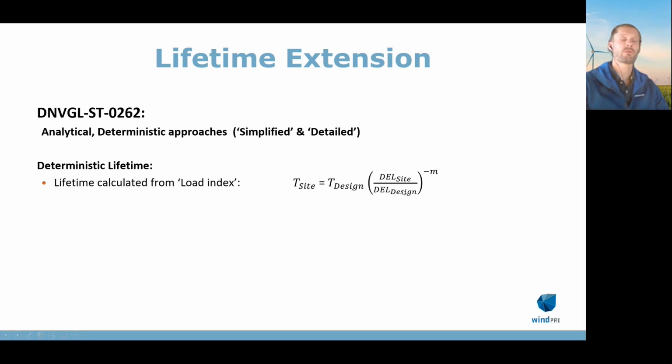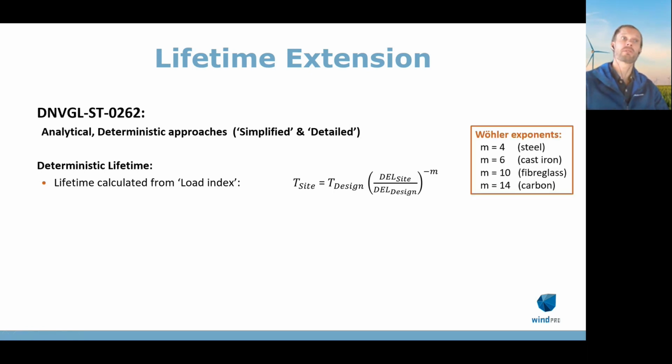And when that is raised to the power of minus m, where m is the Wheeler exponent, this material parameter, where we would have 10 for fiberglass, and multiplied by the design lifetime, you get the estimated lifetime for the site conditions. So this is the relation between design lifetime, load index, and lifetime for a site.